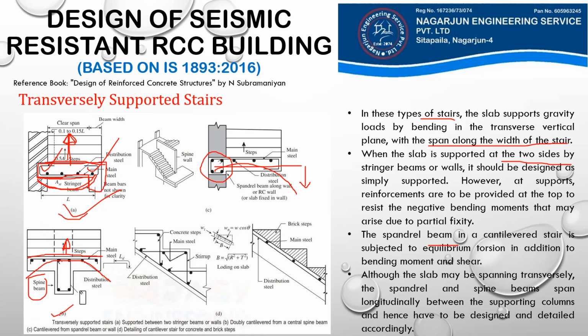Similarly, the behavior of this another type of transversely supported stairs, what it says, although the slab may be spanning transversely, the spandrel and spine beams span longitudinally between the supporting columns and hence have to be designed and detailed accordingly. So you see that the steps of this staircase are spanning transversely, but still this spandrel beam in this diagram or our spine beam in this diagram, they are spanning longitudinally because these beams